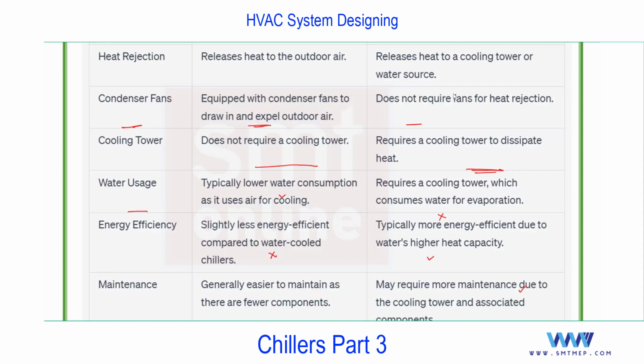But that is not the only point, because in some cases the outside temperature is above, say 40, 45 or more, but there is scarcity of water. In that case there is no choice for the water cooled chiller. You need to compromise with the air cooled chiller. But if you have both options, in that case you can take the decision accordingly as per the condition.